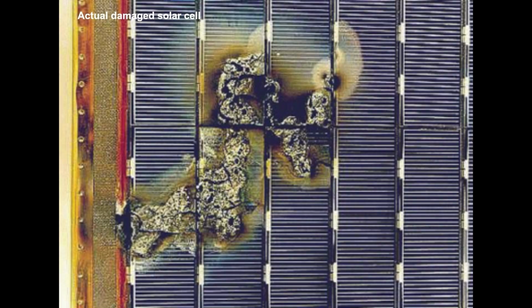With that, we can solve for the balance of charge near the surface and assess if a dielectric material will charge differently from a conductive material. In some cases, the differential charging between the two is so high that we're going to have an ESD that will be generated. ESD stands for an electrostatic discharge, and the consequences are very drastic. We can get full damage to the component, or we can get just some RF interference with other equipment.